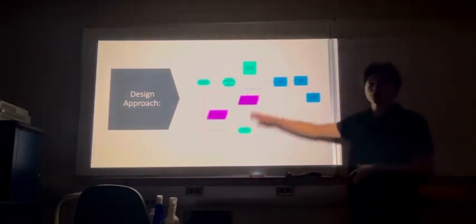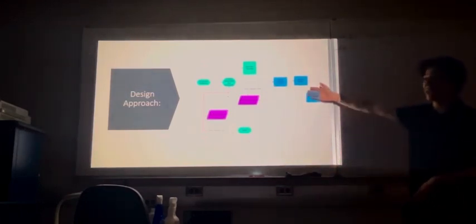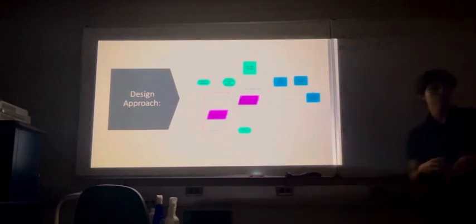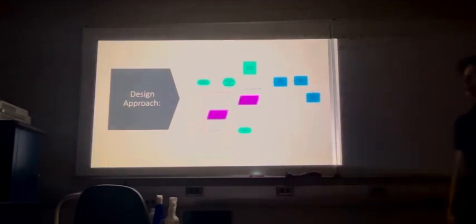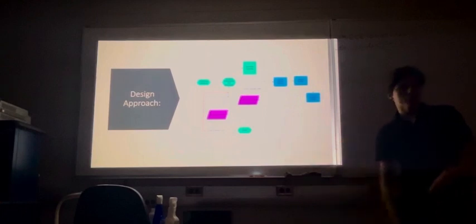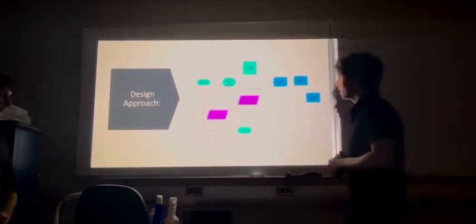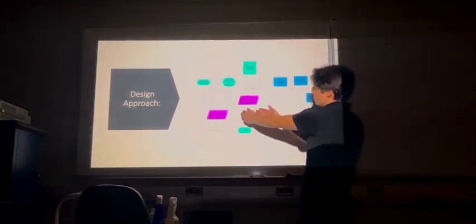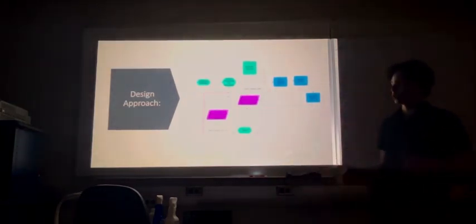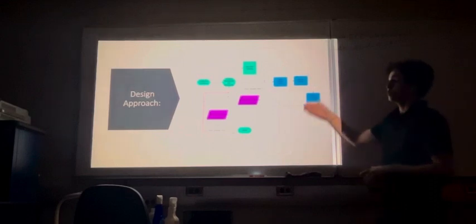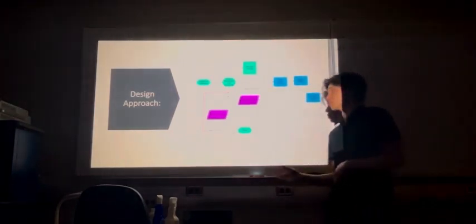Then we derive the transfer function for each of these topologies, and then create our own analog filter wizard for these, which is done in MATLAB, which we'll also demonstrate later. This analog filter wizard is pretty interactive. I think it's pretty cool. It allows us to compute the component values. Right after that, we go straight to the simulation. We simulate it, make sure everything's working well, and make sure that our actual component values are aligning to the correct frequencies that we want them to.